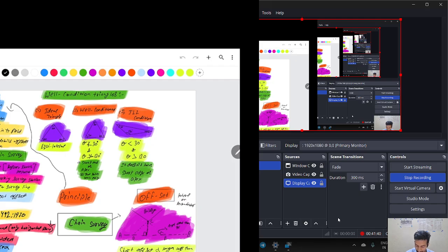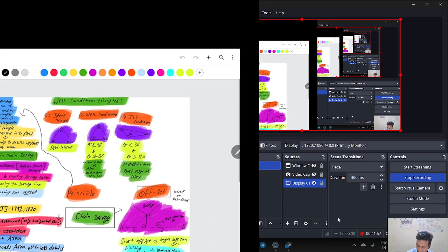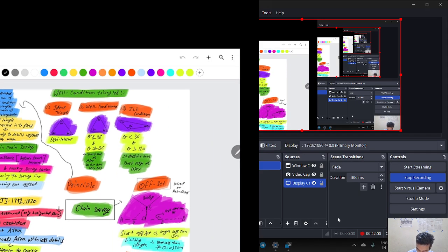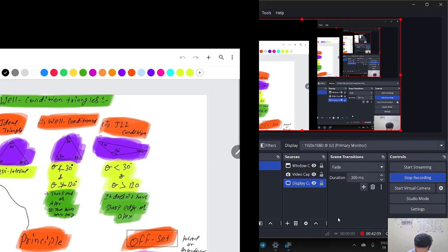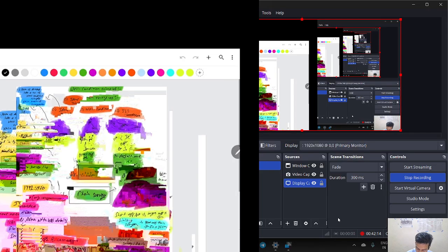And the second is the well-conditioned triangle, where theta is not less than 30 degrees and not greater than 120 degrees, and sharp end or apex, so data points can be located easily. But in ill-conditioned, there is no such limit. Theta can be less than 30 degrees or greater than 120 degrees. This is not valid. You have to remember only the two well-conditioned triangles.